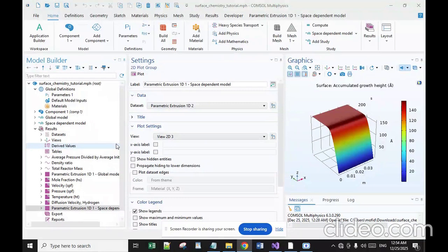This reaction is usually performed in LPCVD systems with either pure silane feedstock or a solution of silane with 70 to 80% nitrogen. Temperatures between 600 and 650 degrees centigrade and pressures between 25 and 150 pascal yield a growth rate between 10 and 20 nanometers per minute.